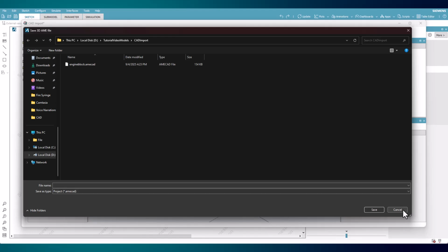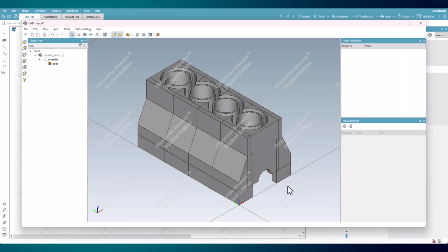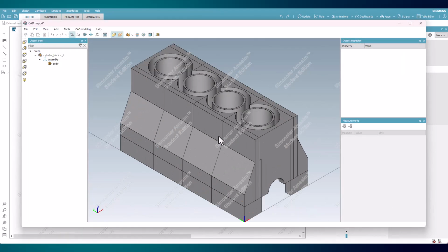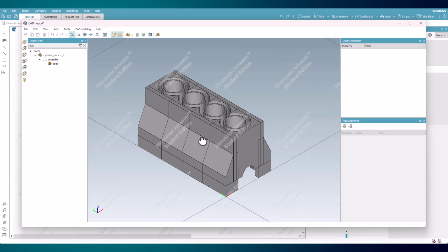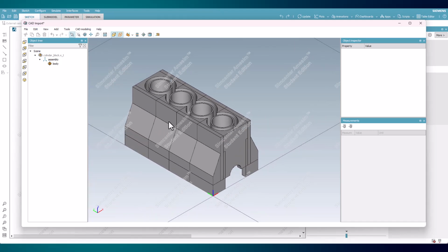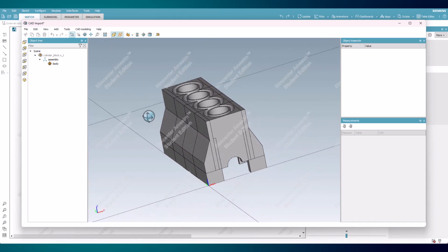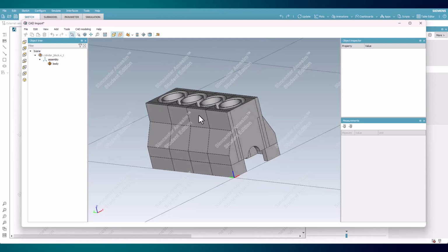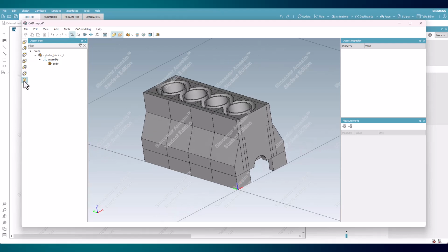In the Scene window, one can navigate around the part by zooming in or out by scrolling on the mouse wheel, panning by holding down the mouse wheel, or rotating it by holding down the right mouse click. Alternatives for each of these functions are available to select from in the top ribbon, and certain views are available to select from to the left.